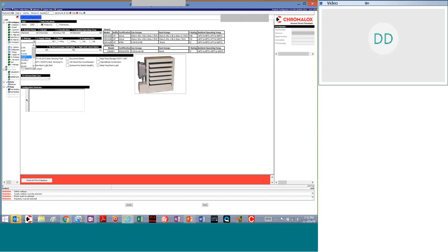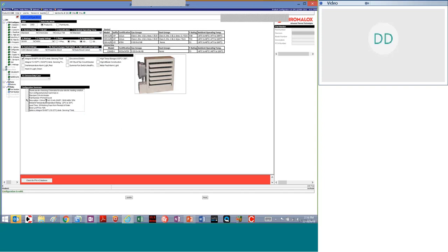The wattages are all pre-selected for you, everything that's in our catalog. Most commonly, 480 design, 3-phase, 60 hertz US, 50 hertz UK and other places, important to remember. Maybe an integral thermostat. Our design is currently, let me get the control voltage here, we'll go 120, open glycol, so we'll go with an auto cutout. So you may see CXHA. Now that's the standard design, but if I click this high altitude design, it became a B.